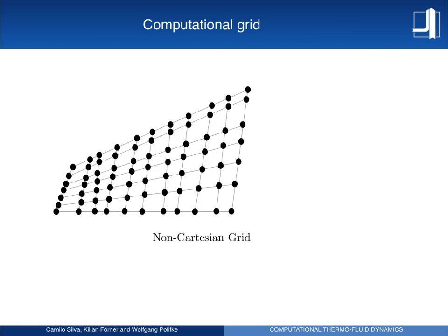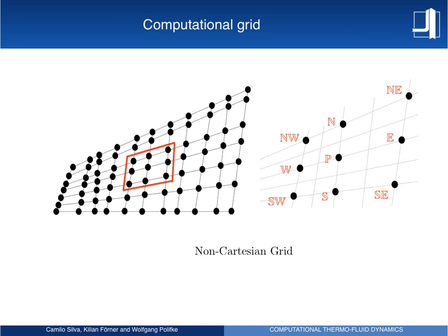in order to have a better understanding of the methodology, we will still consider a non-Cartesian grid, so something that looks like this in a much more organized way than the thing I just showed you before. But it doesn't mean that it does not apply for the mesh I just showed you before. Okay, we will just do the derivation from this kind of system, but it can be applied in more complex geometrical domains. And if we just visualize the 9 nodes I just showed you before, we have the same situation here. We have the node P and the 8 neighbors if we're looking at this region in here.